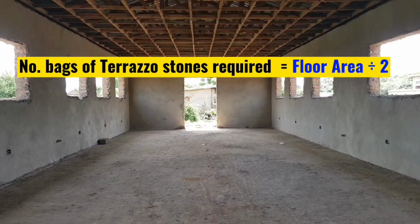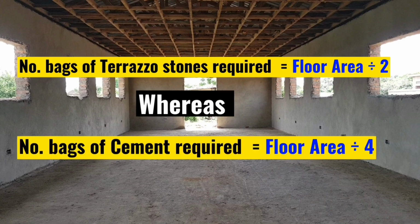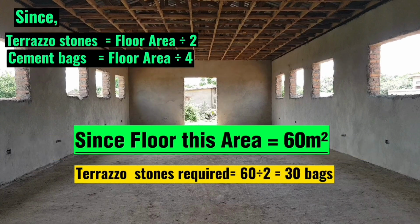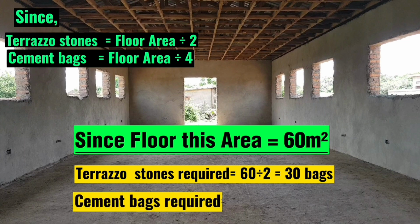The number of bags of terrazzo aggregates or stones required will be equal to floor area divided by 2, whereas bags of cement required will be equal to floor area divided by 4. Therefore, for our case here, we need 60 divided by 2, which gives us 30 bags of aggregates or stones, and 60 divided by 4, which gives us 15 bags of cement.